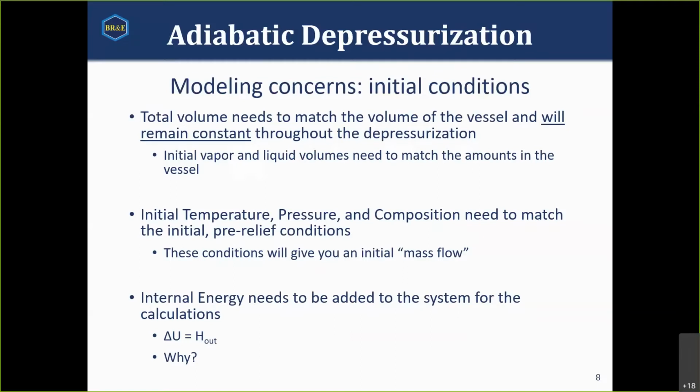When we are setting up our system, we need to set it up to where the initial pressure, temperature, and composition match the pre-relief conditions. This does not mean, and we'll go into this in more detail, for example, the values that ProMax is telling you in your stream or in your vessel, your separator, your pipeline. The conditions in that stream may not be the conditions in your separator, in particular if you have holdup times. We know the initial temperature, pressure, composition. We know the total volume of our system.